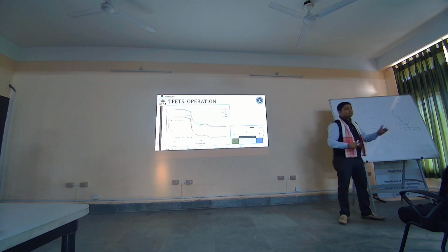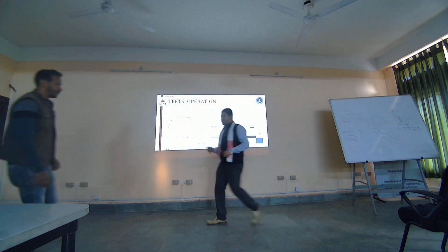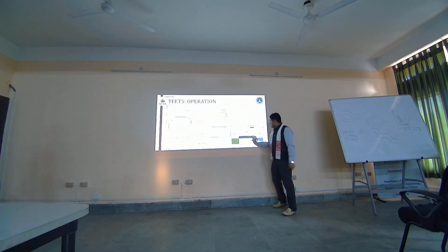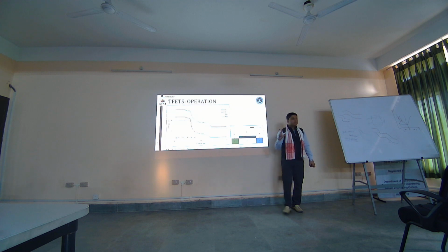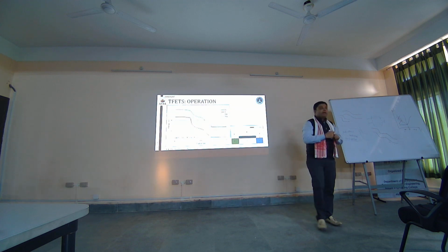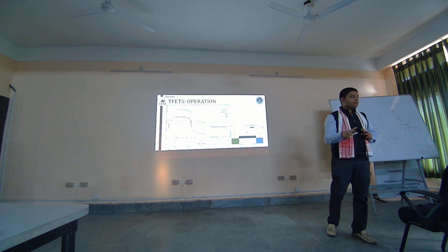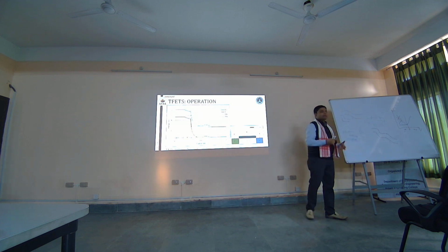So these two techniques: one is the gate drain underlap, and one is the change of doping concentration in the drain. So basically it is known as the asymmetric doping method for the source and drain interface. That is one technique, and gate drain underlap is the second.